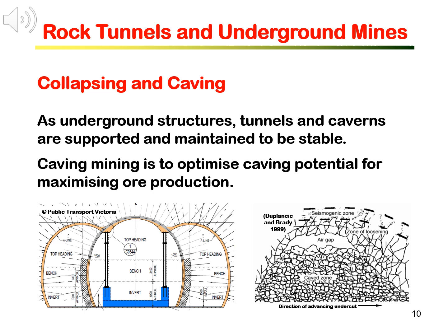In fact, as we will see later, both stability and capability are governed by rock mass quality, and both are assessed by RMR and the Q rock mass classifications. Capability can perhaps be viewed as limit of stability of unsupported rock cavern.